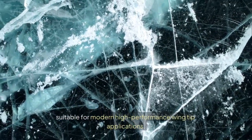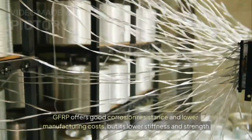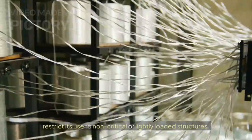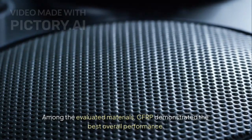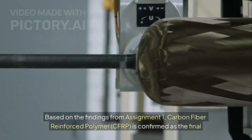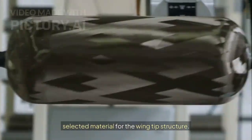modern high-performance wingtip applications. GFRP offers good corrosion resistance and lower manufacturing costs, but its lower stiffness and strength restrict its use to non-critical or lightly loaded structures. Among the evaluated materials, CFRP demonstrated the best overall performance. Based on the findings from Assignment 1, carbon fiber reinforced polymer, CFRP, is confirmed as the final selected material for the wingtip structure.